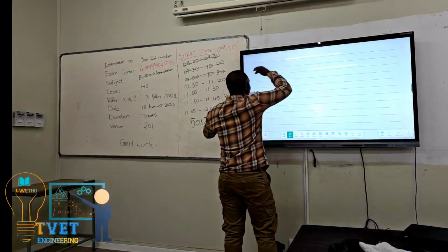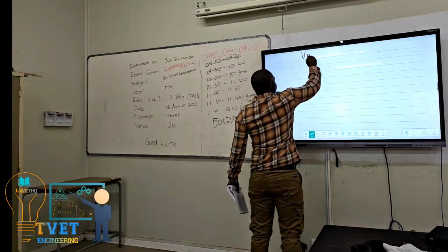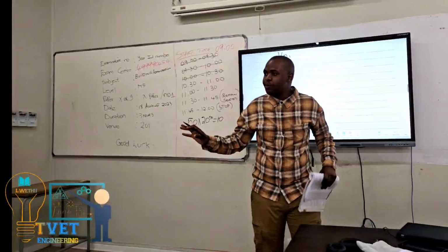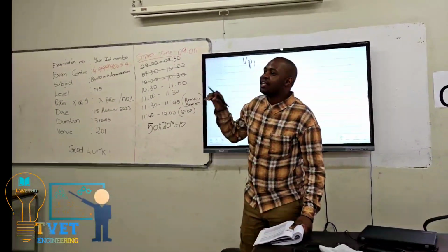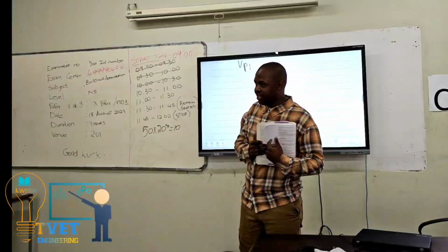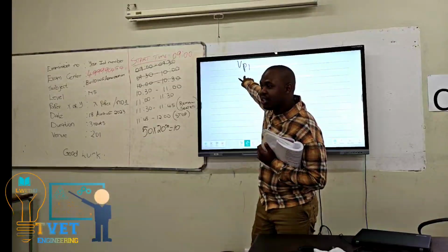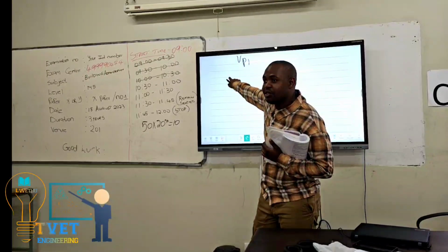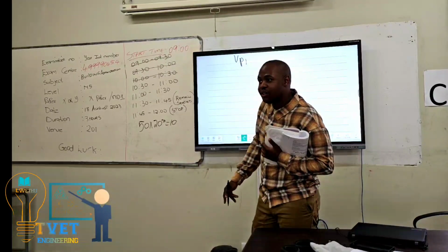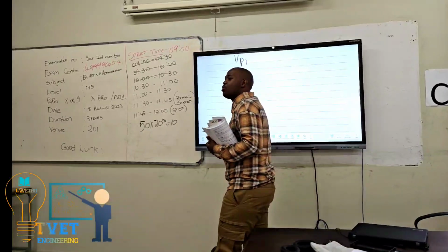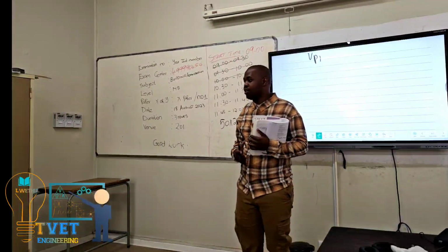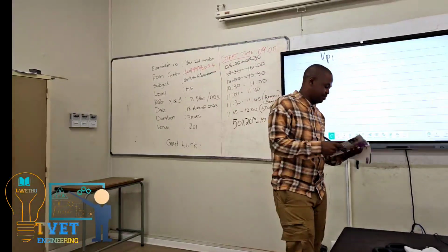Remember, and I have always said this, when you are working with 3 phase in calculations, we are always working with one phase, the per-phase or balanced line value. That is why I must always convert to one phase.